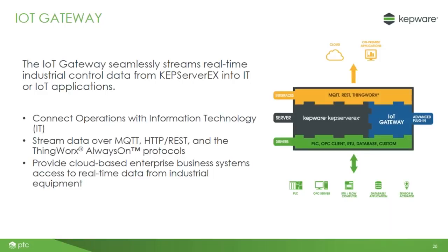And then we have something that sort of lives alongside. It's all one application, but we have these plugins that extend the features and functionality of Kepware. And so what we were leveraging today was our IoT Gateway plugin that hosts IoT-centric, we could say, web service-centric or IoT platform-centric protocols. And we can connect to different IT systems. We do support SNMP alongside HTTP and MQTT. However, what we found is that most IT teams would prefer to use something lightweight and simple like HTTP versus something heavier weight like SNMP for just moving data out of a process control system.